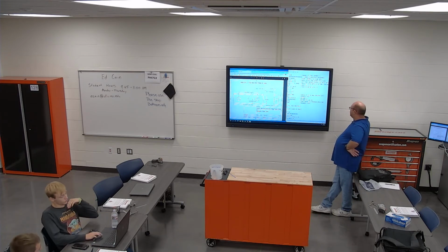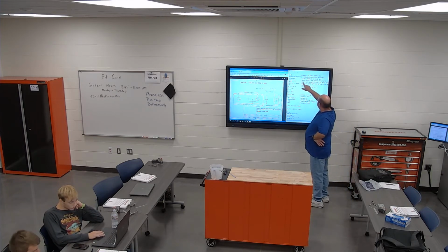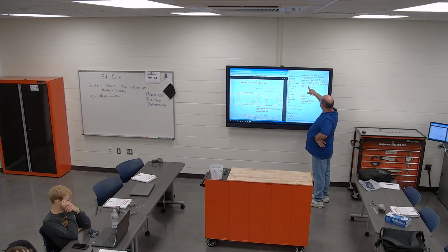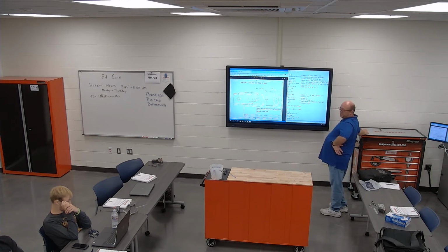That's fine, thank you. These little notes off to the side help you, so when you forget, G43, tool height offset. This side here, a little bit of feed rate of 25, turbo coolant. You can't see the rest. Move to Z0, feed rate. So you can follow these little notes. I'll try to help you as much as I can. I'll type the next one when we go over it in class probably. I don't like doing it this way. I'm going to try to do it like I do the videos.